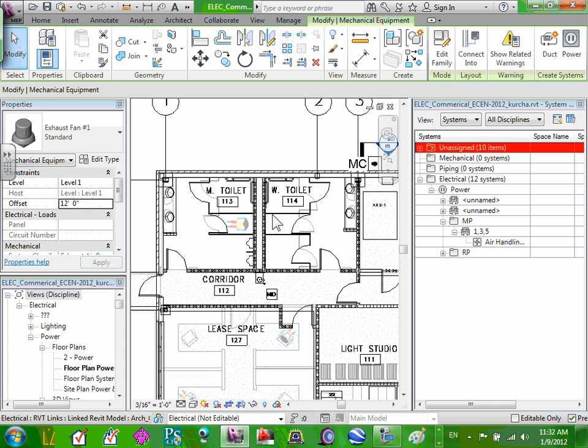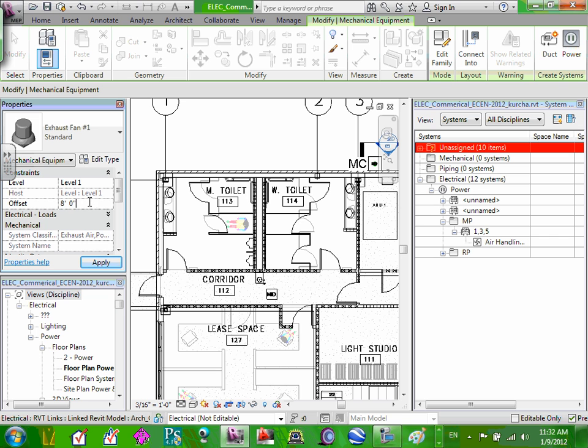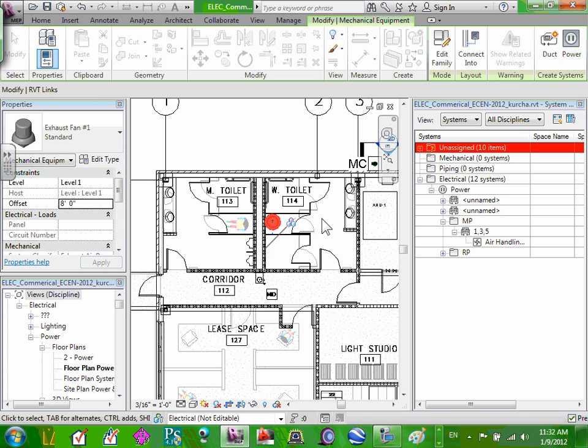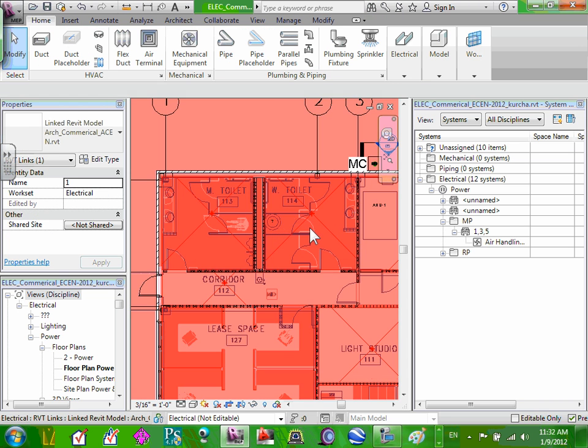Do you see why it disappears, guys? Because you moved it beyond the limit of the cut plane. That's the problem with Revit: if you don't set your views, things disappear based on the height. You're moving things higher than what we did. So I'm going to put it at 8 and see. Well, we could just keep it at 4 and then play with it. Why don't you guys set it at 8 now until we can adjust the view, just for the time being?